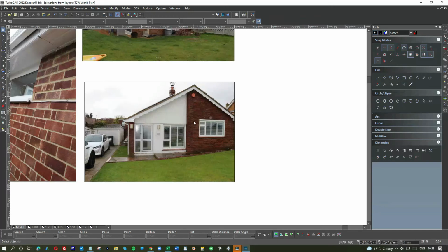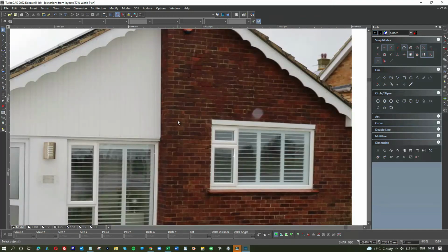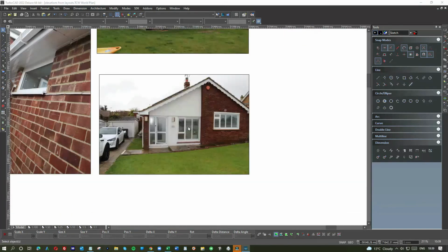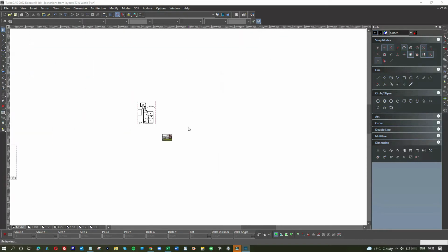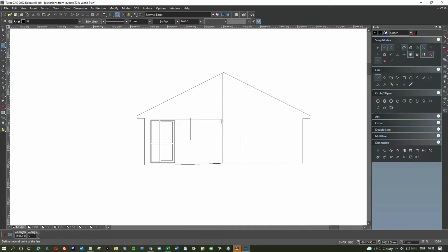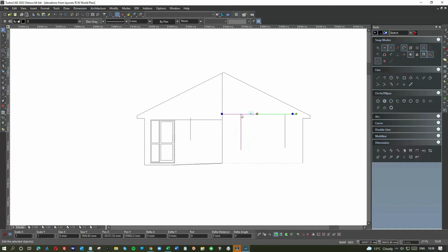So now, because we've stepped up, how many bricks have we stepped up? 1, 2, 3, 4. Forget the lintel. We've stepped up 4 bricks. So 4 bricks. That's the bedroom window. I'm ignoring this window, so we can do that one first, I guess. But I'll put the line in now that I've checked. So from here it's 75 times 4, 300. Tab 3. So that's the line for the next window. We'll work out the bottom in a moment.